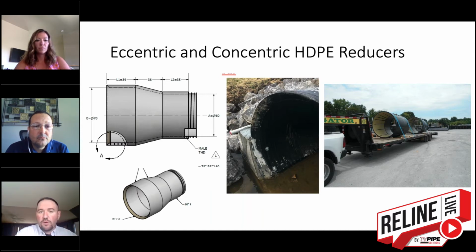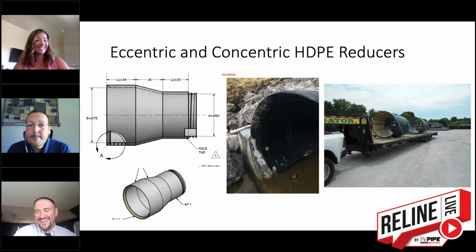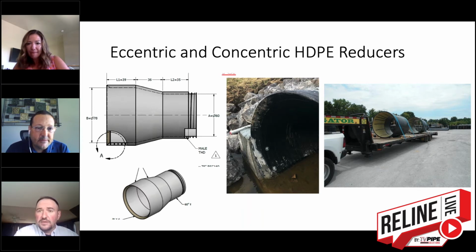And then you see one with a cutoff wall built into it in the center photo. And on the right-hand side, that's actually one we put in Southern New York. That's a profile wall HDPE to solid wall connection chassis. I don't know if you had seen those before. We can make, for example, that 72 by 63 inch, so it went into a 63-inch Snap-Tite reducer. I've seen this done once. Okay, we can jump to the next slide.